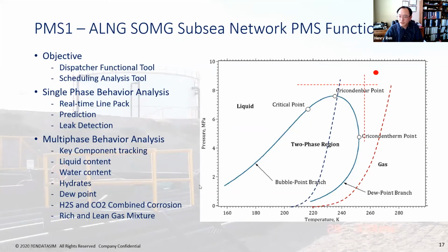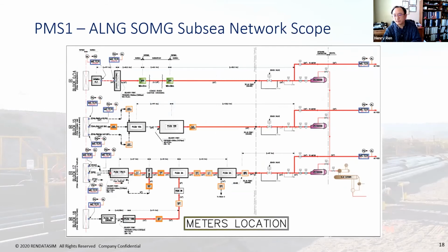Okay, if you have a richer gas, it will be higher. And if you don't change these operating settings in the plant, then by the time you receive the gas, maybe the condensate associated with it, over time you have a hydrate, and you are not even aware of that, for the entire pipeline.